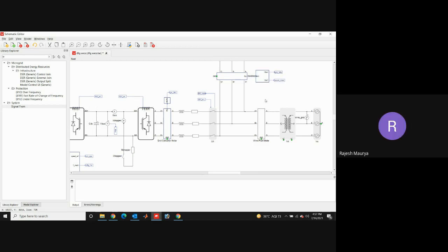So these are the two changes. Sir, there are no matching tags for this WM underscore ref. Yes, it will not match because we have not taken any From block, speed. Speed or REF? WM underscore speed only, not REF. WM underscore speed. Actually, it is not matched because we have not taken any From block to connect with it. Now we'll take it. Okay.